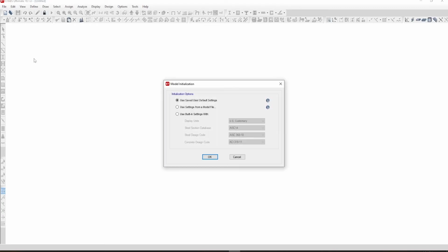The beams are 24 inches wide by 30 inches deep. The building will also be loaded with an additional dead load of 25 pounds per square foot for partitions and equipment, along with a live load of 80 pounds per square foot for both the floors and roof. Lateral loading will be wind loads based on the ASCE 7-10 code.